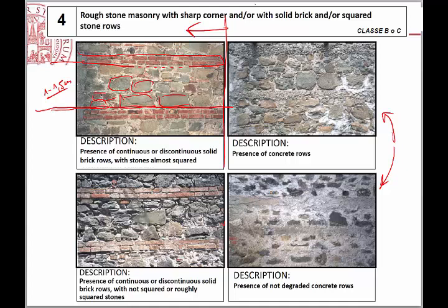For example, 1 meter of masonry. It is like to realize a ring beam, but without any steel. Okay? The idea is just to replicate something similar to the case that we have on the left. Of course, the strength of that concrete transversely is a low quality strength. But it can be sufficient, for example, to avoid some overturning of some walls, etc.